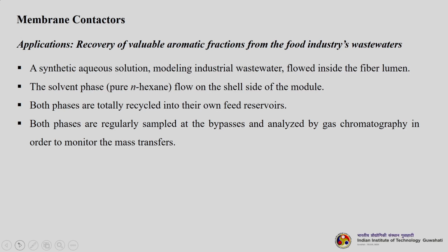A synthetic aqueous solution, which was used as a model industrial wastewater, flowed inside the fiber lumen, the hollow fiber lumen. The solvent phase being used is n-hexane, which flows on the shell side of the module. So, tube side and shell side, let us say this is the tube side, then we have a shell side, something like this.